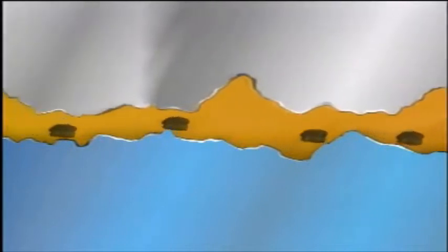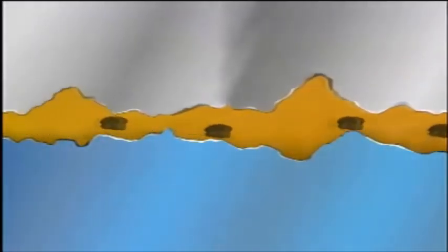The purpose of lubricants is to make two surfaces slide against each other more smoothly, so a lubricant is a substance used to reduce friction. The lubricant separates the two surfaces and reduces the amount of contact between them. To be effective, the lubricant must be clean. If a lubricant contains dirt or other contaminating particles, these particles can bridge the gap created by the lubricant and scrape against the metal surfaces. This increases friction and will eventually result in wear.